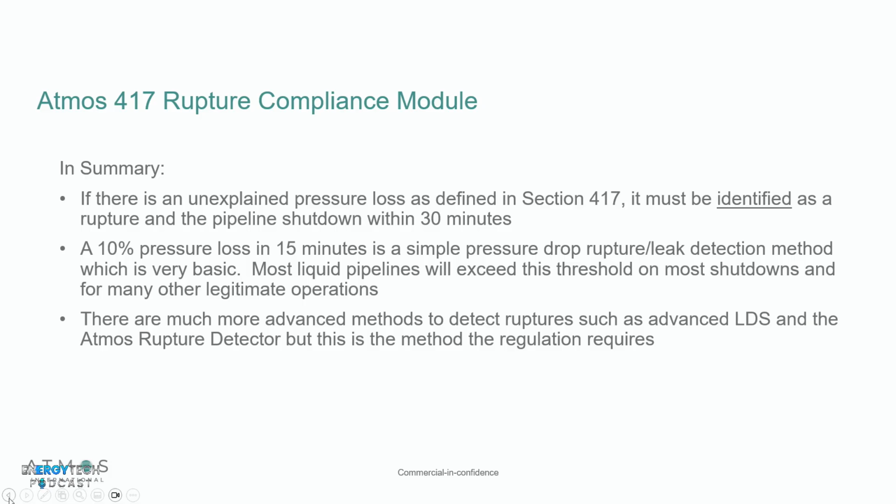The main difficulty with this particular regulation is that most advanced leak detection systems are not pressure drop. So if you have a real-time transient model, or even a negative pressure wave system, it's not doing exactly what the regulation says, and it's very hard to demonstrate it. I mean, you could argue it is doing it, but you couldn't demonstrate it with any ease.